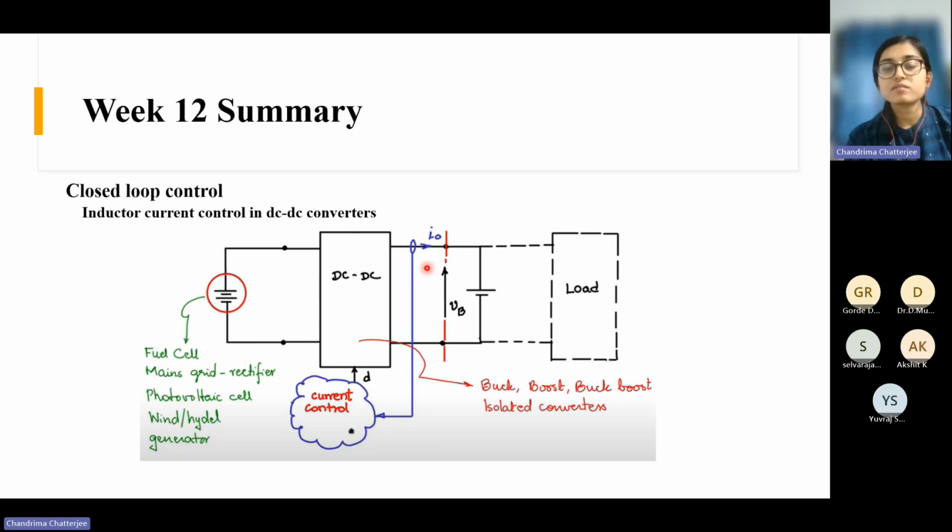If we talk about onboard chargers, then usually it may be single phase, it may be three phase. So there will be the AC grid. After the AC grid, there will be one rectifier and PFC stage, right? So that will maintain the grid current quality.